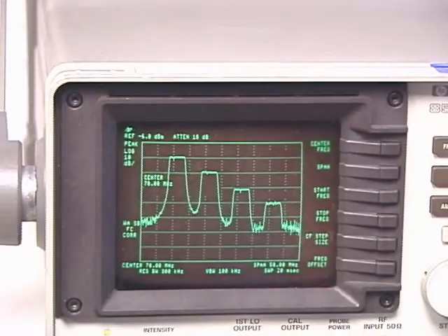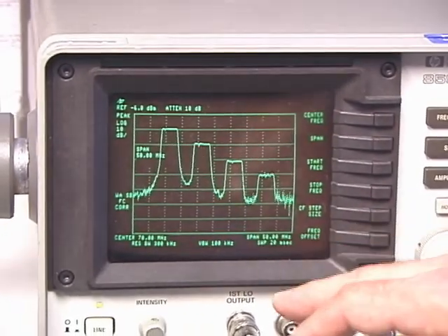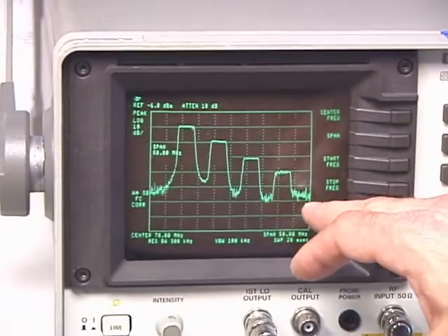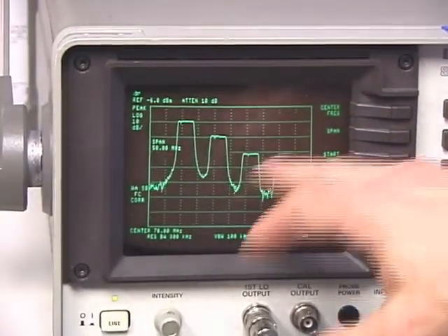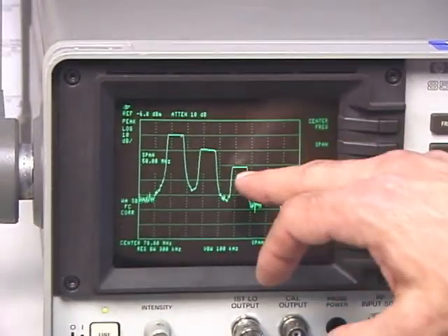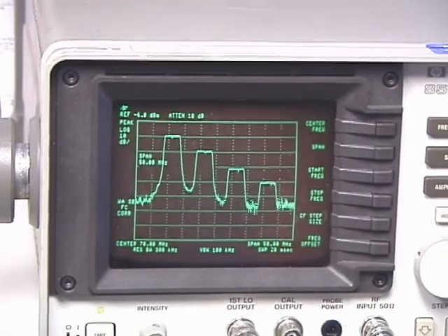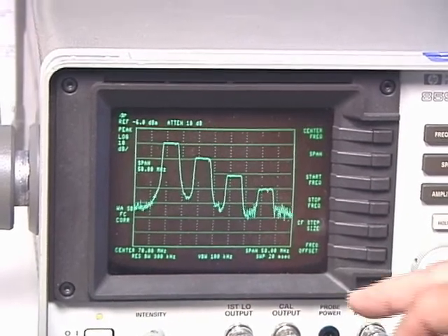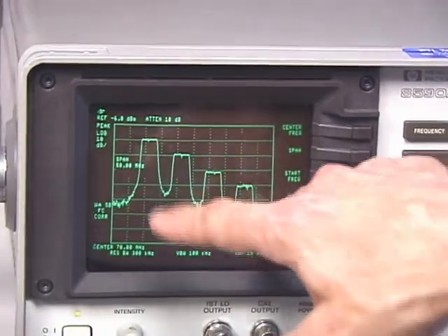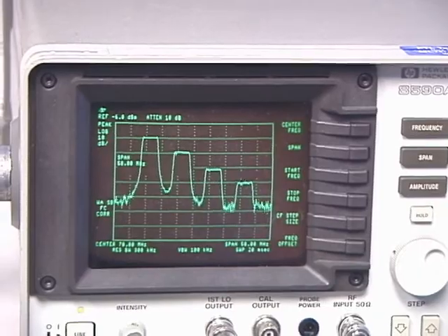The span of frequencies is 50 megahertz. And you can see that we have these 4 bands starting at 55 megahertz, ending at about 85 megahertz. So it's 70 plus or minus 20. And they differ in amplitude by 10 dB. I did this so that when we down convert them with 4 separate DDC channels, we will be able to identify that the DDCs are tuned to different portions of this roughly 50 megahertz span of signal frequency.